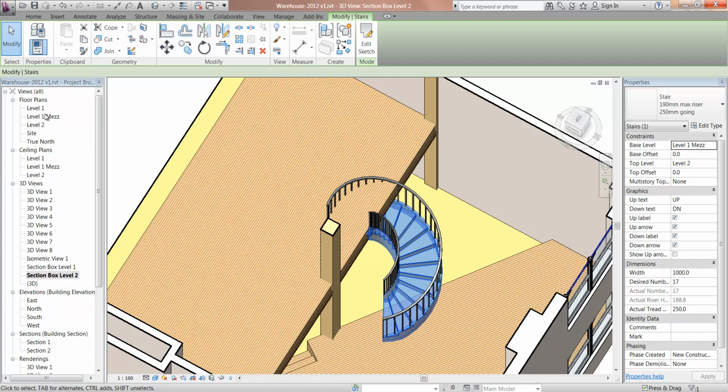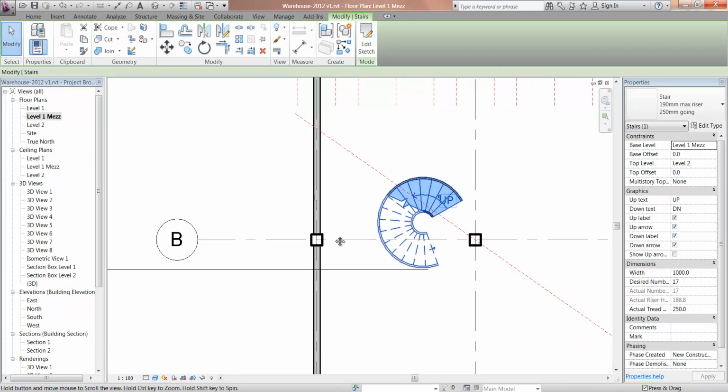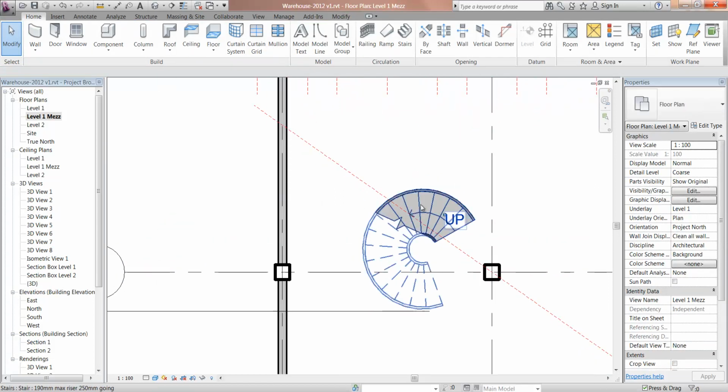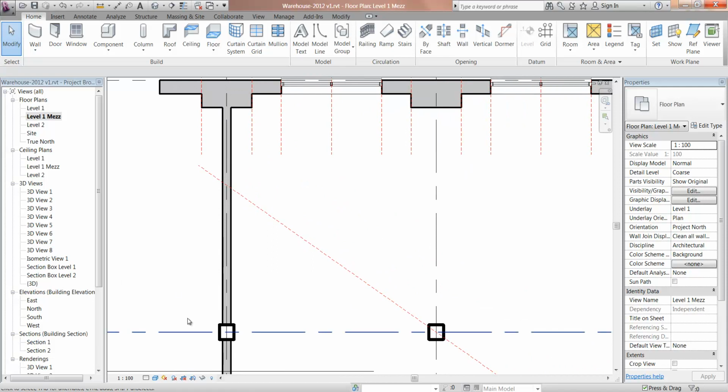So going back to the plan here, if I was going to do a spiral stair, I'm actually going to have a curved stair in the end in this space, but it's not really going to be a spiral. But it's the same principle. I'm going to mark out the centre, and also I'm going to maybe even start setting out the curve as well before I even go to draw my stairs.